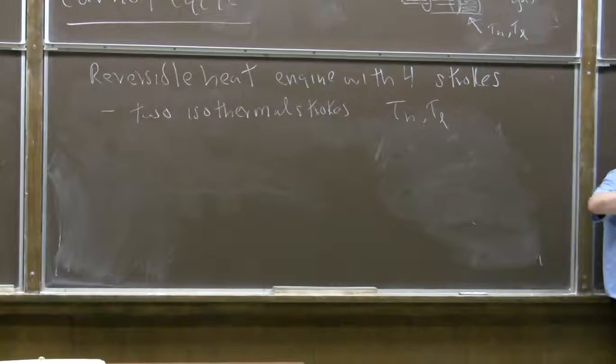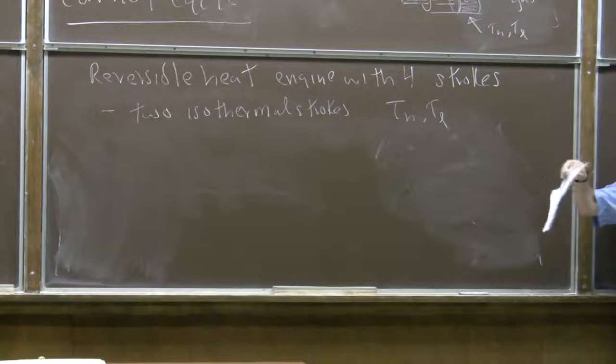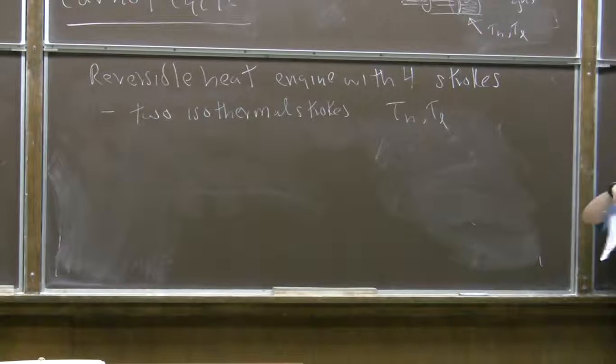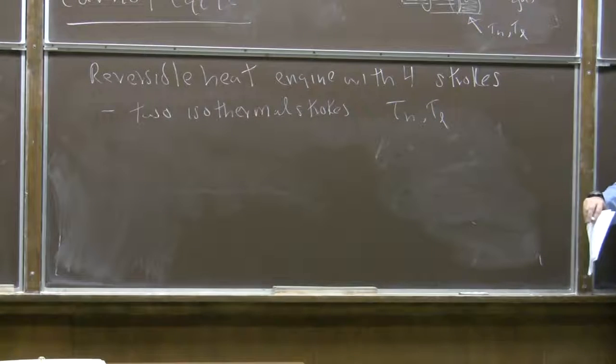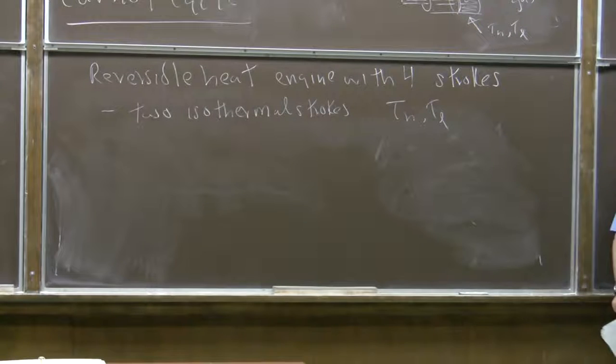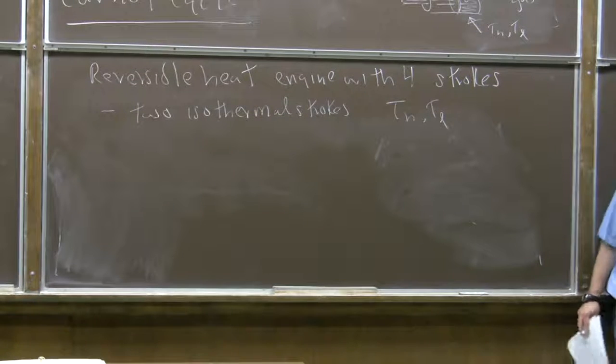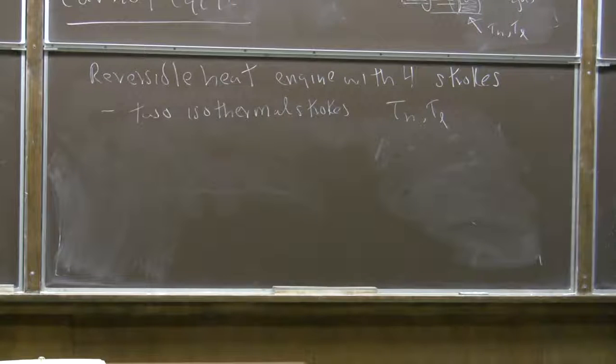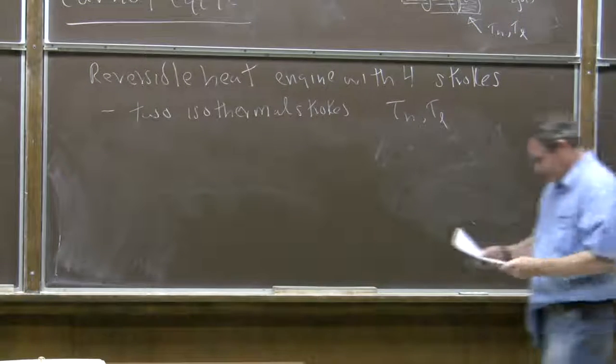At higher temperature, we want to withdraw heat from the high temperature reservoir. So we want to let it expand, right? So that isothermally, heat will come in from the reservoir, the gas will expand and do some work. When it's in contact with the high temperature reservoir, I want to make it a closed cycle, so I'm going to have to compress it again, but I'll do that in contact with the low temperature reservoir to expel some heat to the low temperature reservoir.